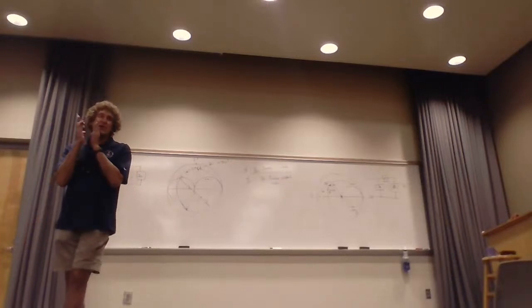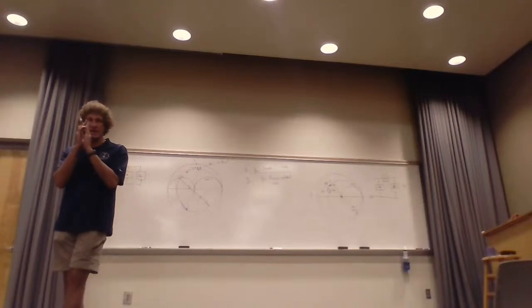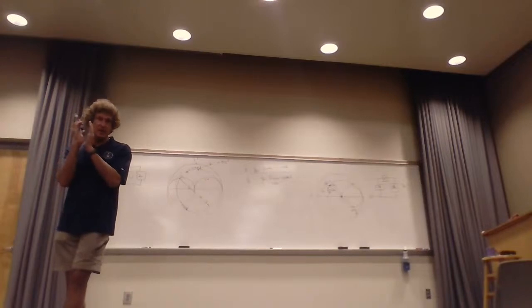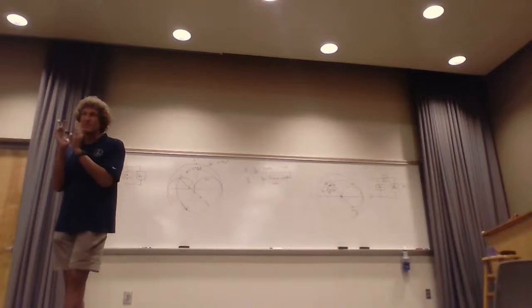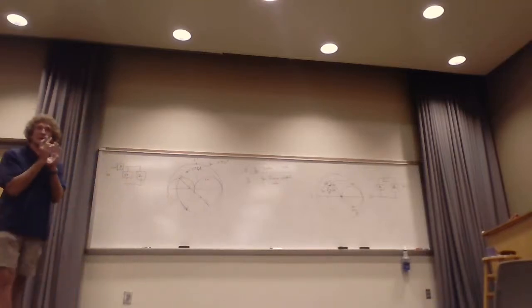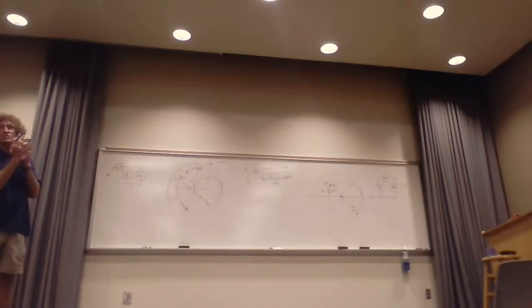And when you have FET front ends, a field effect transistor has an oxide layer, a metal gate, and then you pull up a channel. Or if it's depletion mode, you actually get rid of the channel, you pinch it off. But anyway, you have to get it out of the saturation mode or into the active mode.